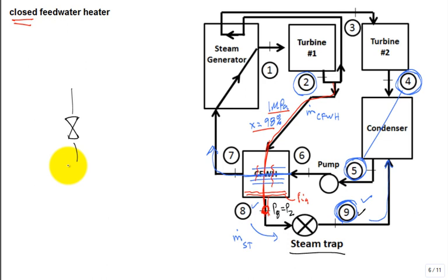It's a police officer who directs traffic. And he says, red light, everybody stops and piles up. And when it piles up, guess what the liquid level does? Goes up. And then he says, oh, I got too big of a pile of liquid back there. Guess what he's going to do? Green light, everybody go. Come on, come on. But only liquid. No steam. I don't want any. I know that there's some vapor coming in here. And if I just said, let it all go, it could drain it, and then I could get steam going through, the vapor going through. And all I want is liquid. And so it's like a float system.